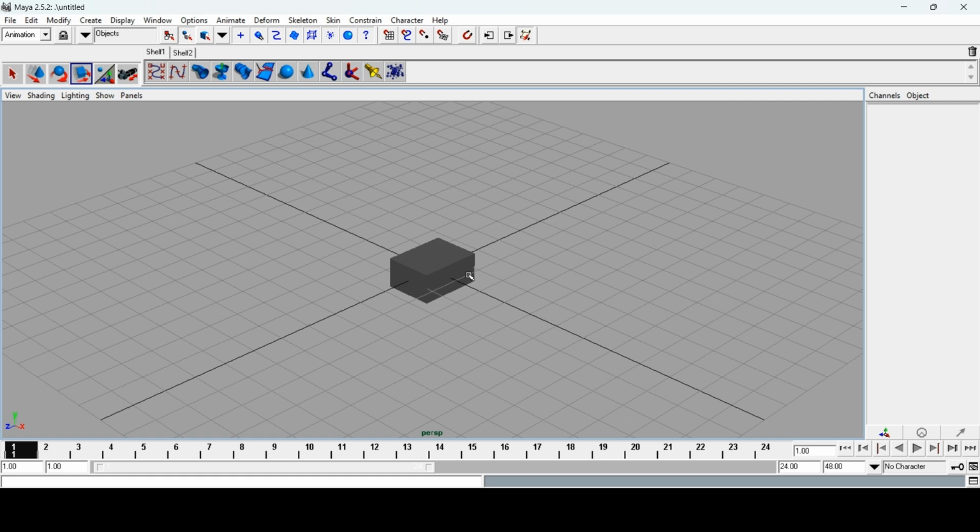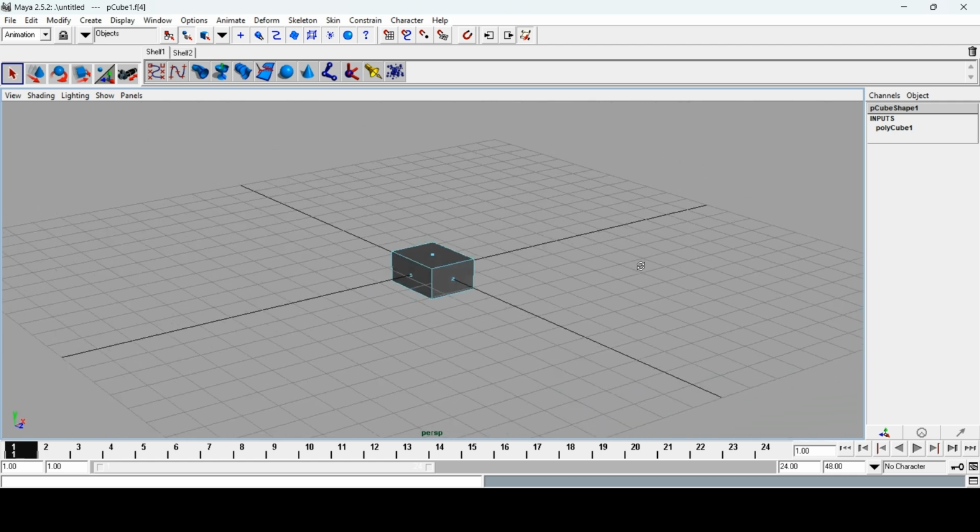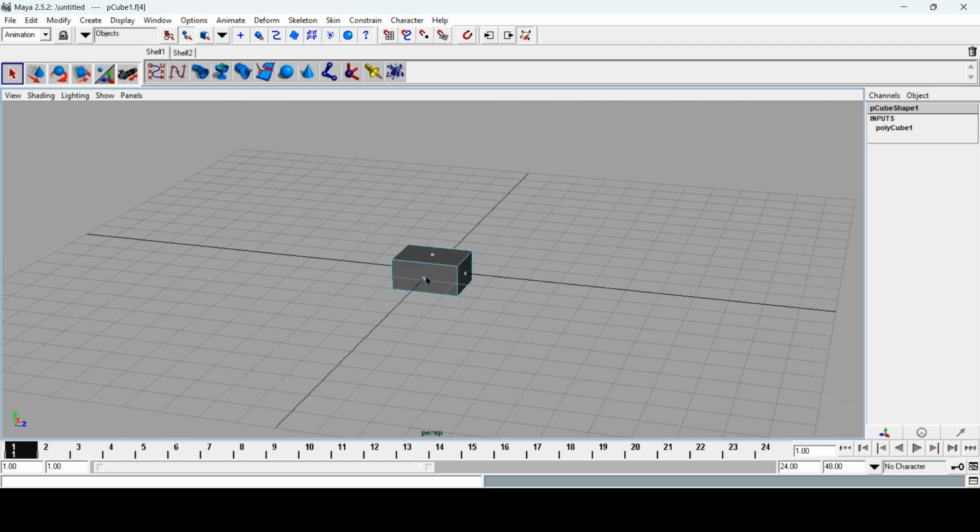We are going to use the extrude function on faces. For this we need to select the faces. For selecting faces we need to right click on the mouse so that we can select faces. Just drag down. Now we can see the faces have appeared. Just select two faces on opposite sides. Alt plus left click of the mouse is used for rotating.